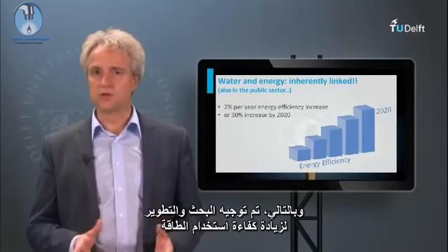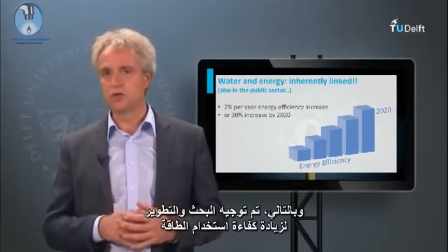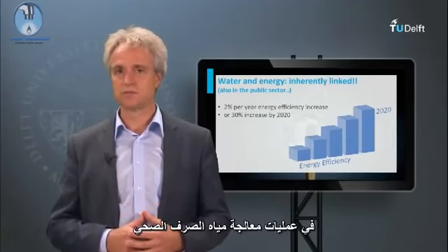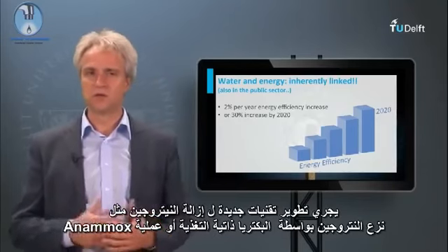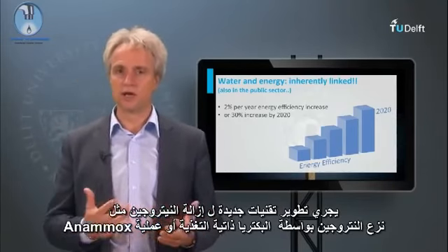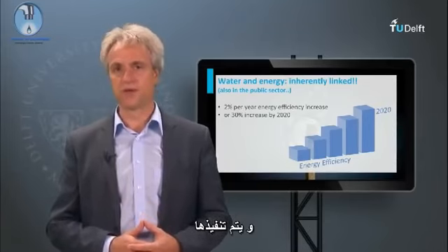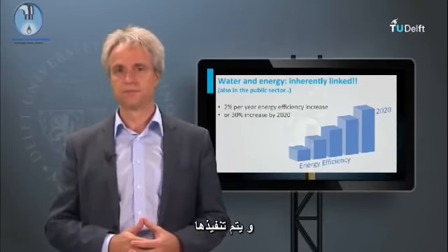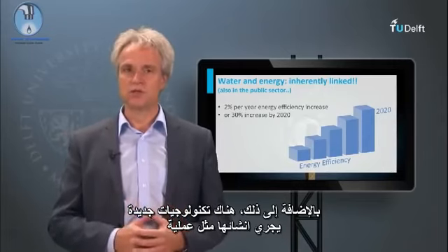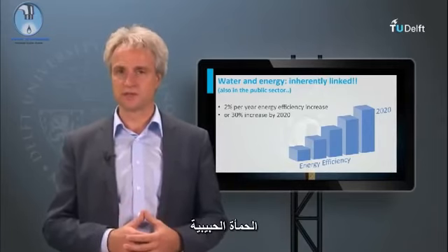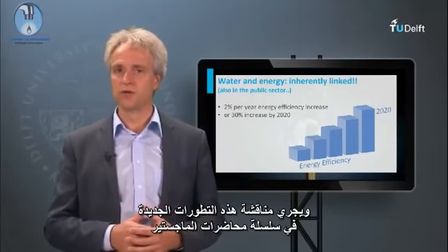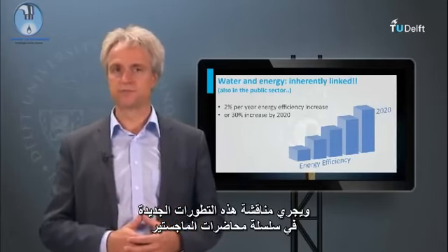Therefore, present research and development is oriented to increase the energy efficiency in sewage treatment processes. Novel technologies for nitrogen removal, such as autotrophic denitrification or NMX processes, are being developed and implemented. In addition, completely different technologies are being installed, such as the aerobic granular sludge process. These novel developments are being discussed further in our Master's lecture series.